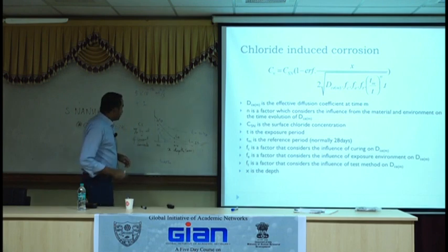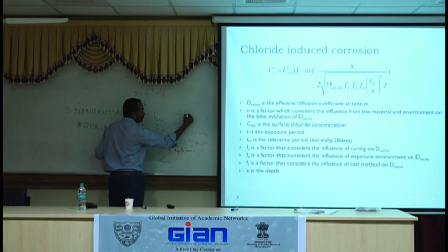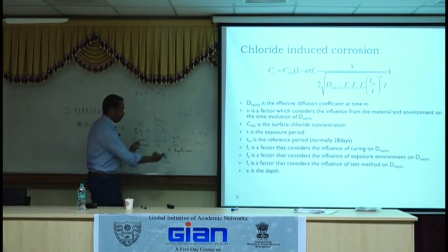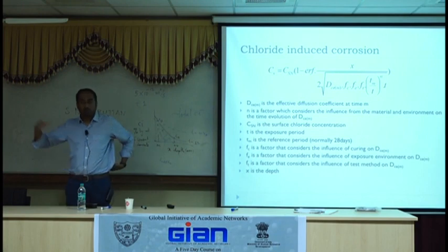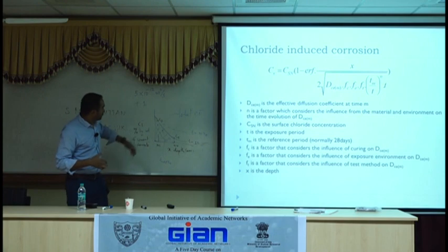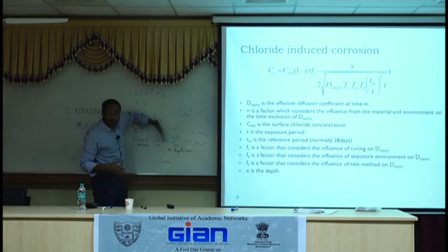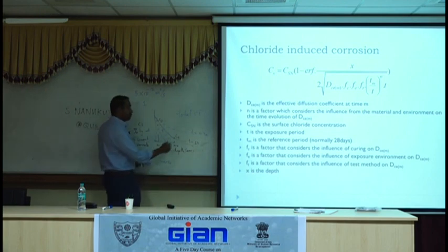For those who know this differently, the area under this graph will give you the total chlorides up to that depth. Okay. So the total chloride will always increase because there's concentration outside, there's not enough concentration inside, so chlorides will always move, which means with time you're expecting the graph to go up and up and up. The critical part to you is, where is your rebar?